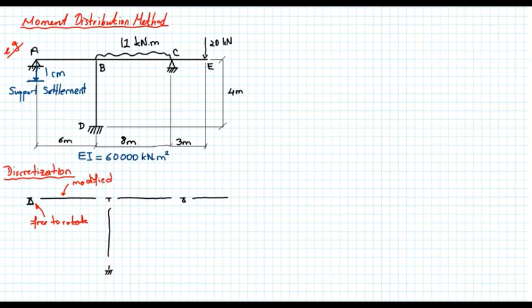So I don't have to define any rotational degrees of freedom at point A. At point B, I have a rotational degree of freedom, theta B. Member BC, let's take a look at point C. Yes, I have a cantilever here, but without the loading, I know that this point C is also free to rotate.